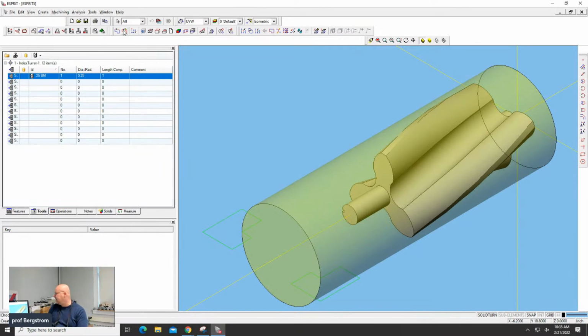All right. So what James and I think we need to do is a wrap contouring or wrap pocketing operation. It's because it's got the 2 twists. If it was straight, a wrap contour would do it. We could make a chain that defines it and run that across. And it's been 10 years since I've done one of these, but I figured it out that time.